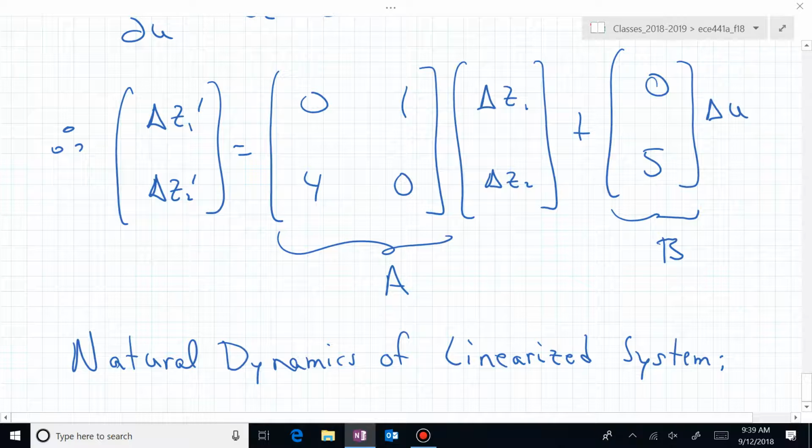We don't need to. What can we associate with the poles of the transfer function in the time domain expression? The eigenvalues of that A matrix. The eigenvalues of the system matrix give us information about the natural behavior of the system. And if it's not like we want, then we figure out, how do we inject U input to change those dynamical behaviors or that dynamics.